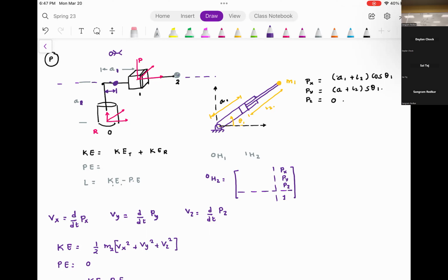So if you really want to see what's going to happen, we will have to assign the coordinate frames, go through the homogeneous transformation, but at the end of the day, this is what is going to happen. You are going to have this distance A1, this distance plus this distance which is L2. And when you take a look at this total distance, it is nothing but this radius, it will have its cosine component and it will have its sine component. Everyone understood? But in this case, I don't think it is true duality. It's bounded in the vertical plane.